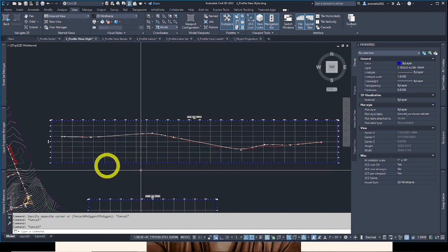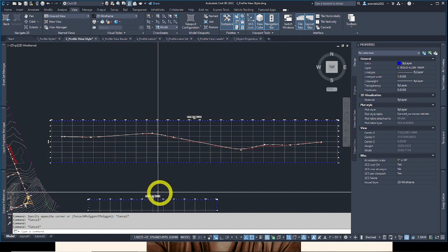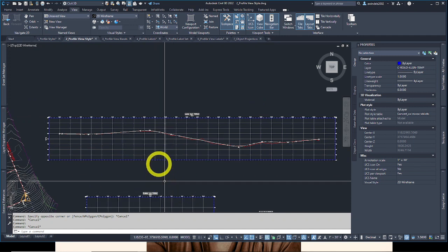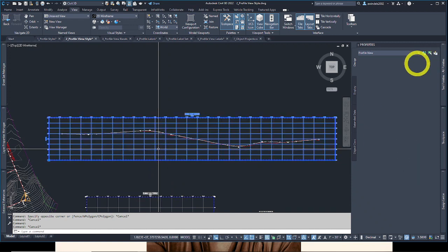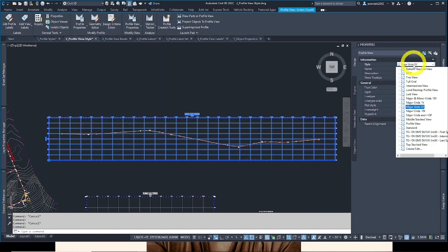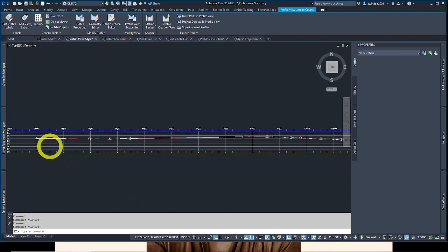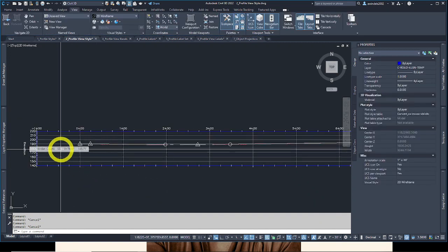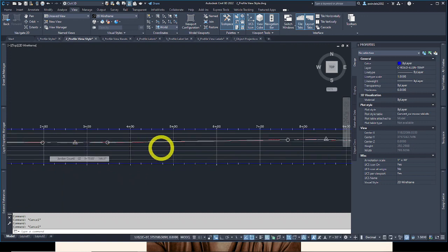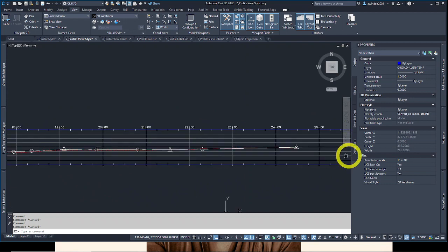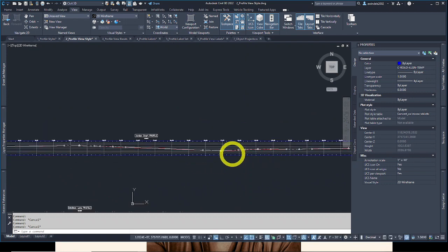The vertical exaggeration, like I've said before, is reduced to 5 on this one. It makes the profile, of course, feel much flatter. And lastly, we'll bring it down to 1, like I was saying before. It makes it so there's no exaggeration, very flat. So the flatter the earth that you're doing these on, the more you probably have to do exaggeration to really get it to show graphically some significance in elevation change.